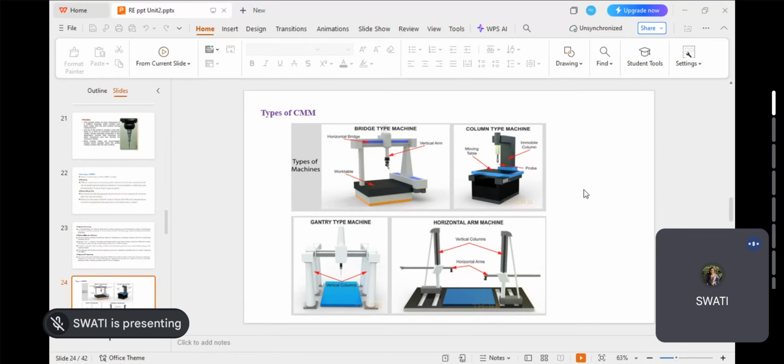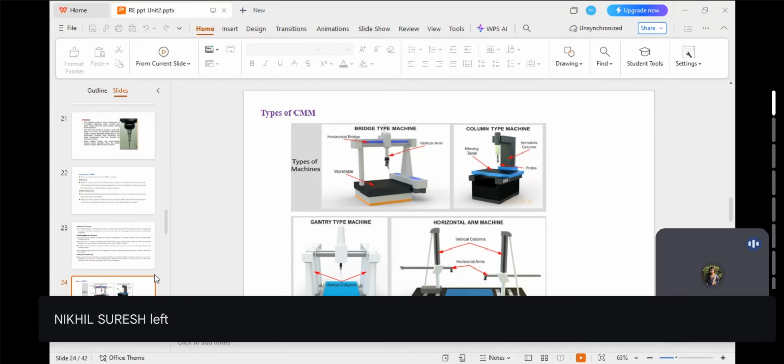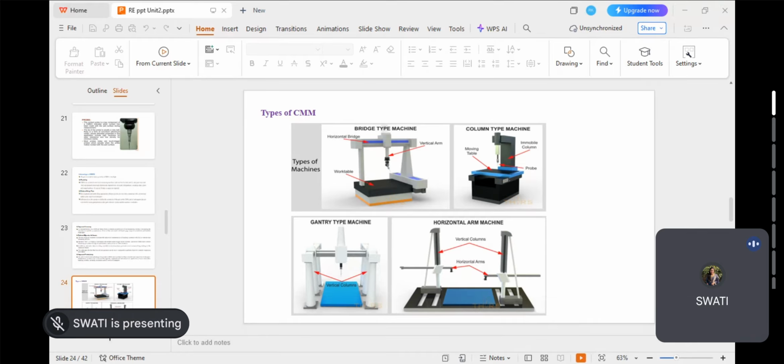That is why the size of the workstation is comparatively small compared to others, like the gantry and the bridge one. It is typically limited to small and medium sized machines because of the small floor space requirement. Parts larger than the machine table can be inserted into the open side without inhibiting full machine travel.